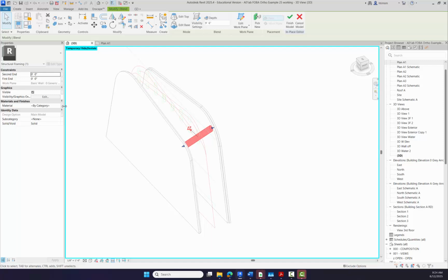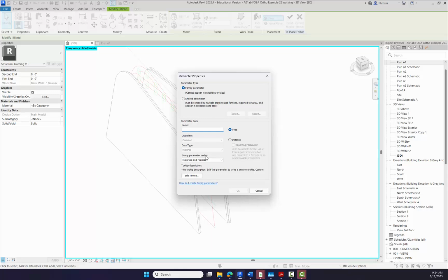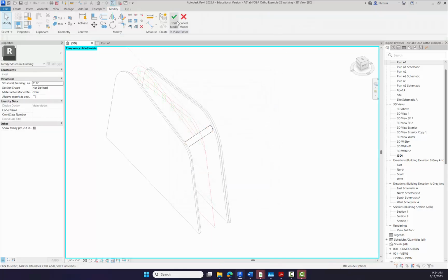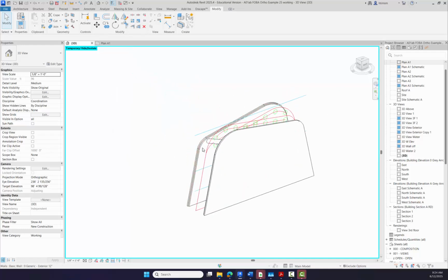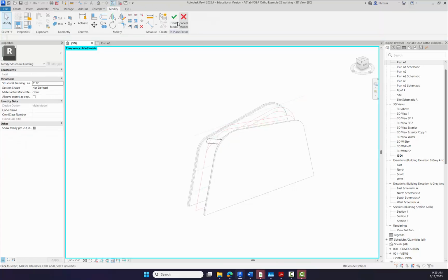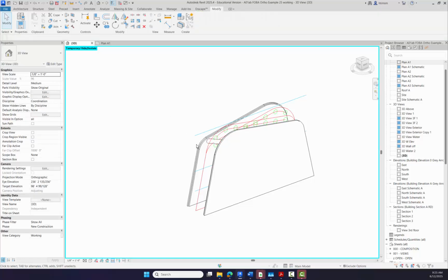You can also come in and add a material parameter to them, right? So beam mat, add an instance, click OK, OK. And then once you finish the model, you go in and just do all the rest of them. To get back in the model, you pick it and edit it in place, right? Finish the model. So there's this guy, and then you'll see there's the beam mat. So that's how you would go through and do those guys.